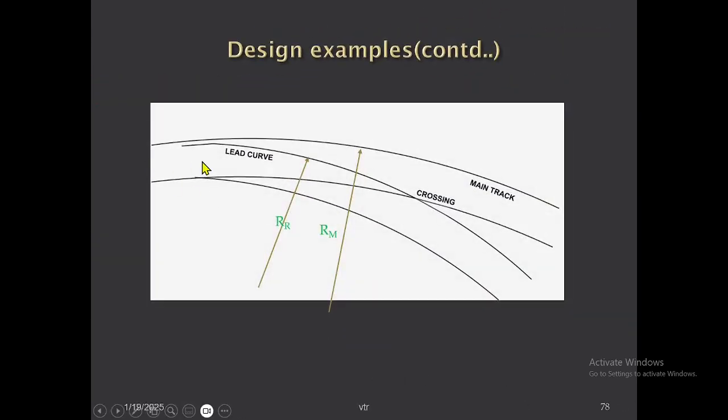So here, this is your main line track, 800 meter radius. This is a straight turnout 1 in 12. Actually, for a straight turnout, 441 will be there. Since the main line is flexing, automatically this also shifted inside. Further, it becomes sharper. So the resultant radius will become around 200 something. Okay. So as discussed earlier, this is the way you get the resultant radius.